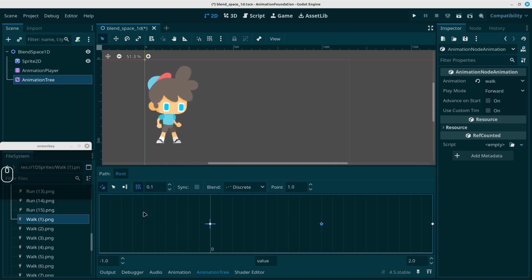And here I just want to use the move backwards, which is the last animation that we made. Let's just add it here, add animation, and walk backwards. And that's it. Let's save this. Let's click the crosshairs. I want you to see what's going on. It's like a slider scale now. If we move to the right, when we move to the center around there, he starts walking.